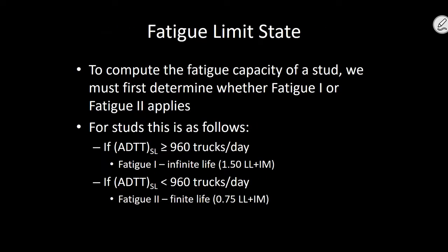Now, let's talk about fatigue, okay? First off, we have to determine whether or not we're in fatigue 1 or fatigue 2. Because we're dealing with studs and we know it's a stud, we don't have to deal with A, B prime, D, or what have you. We don't have to deal with a fatigue category. We know it's a stud. The threshold for fatigue 1 versus fatigue 2 for studs is 960 trucks per day. Usually what I do, though, is I just say, you know what, let's just go with infinite life just to keep it simple. I just keep it basic and say, let's just go with infinite life.